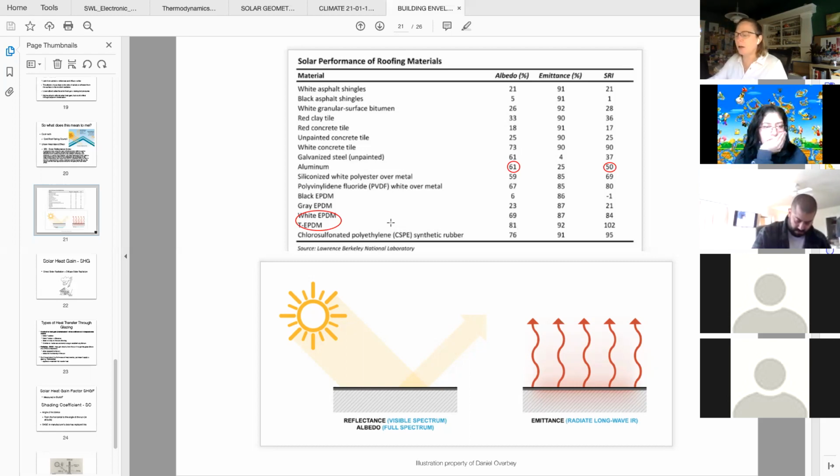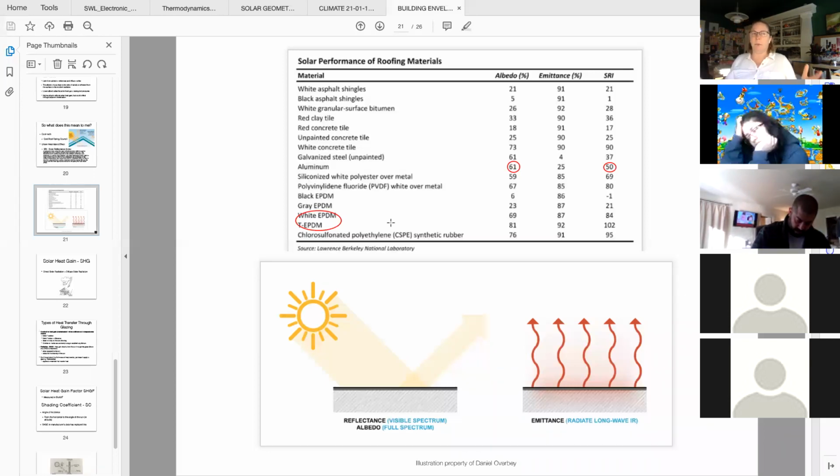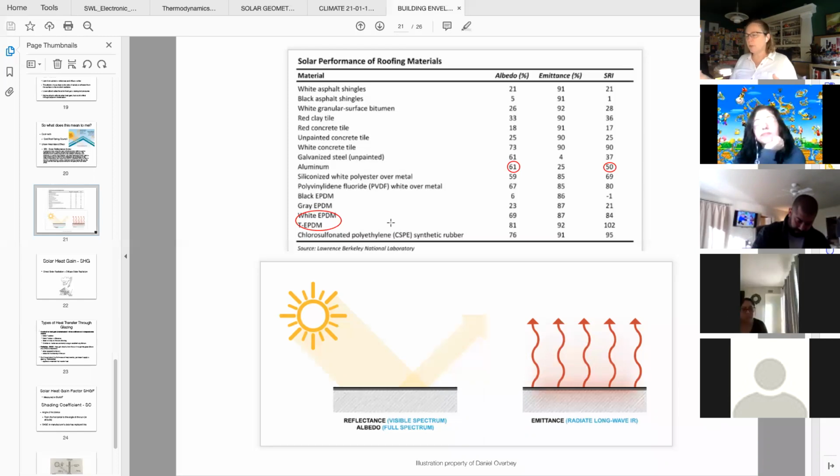It's some sort of polymer, not exactly a natural product, but if you have a really big flat building with a very large roof surface, it's worth it for you. Typically it's worth it in a high cooling condition, where you have a high cooling load, to put on a really highly reflective roof, so to keep your cooling load on your building down.